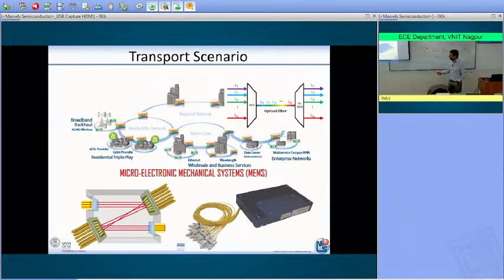However, the time to switch from one port to the other is a few milliseconds. The reason is that you need to control the mirrors in a very precise way in order to align the light output to the proper fiber. It is the time that it takes the mirrors to align and steer the beam to the proper fiber that determines the speed at which the rerouting occurs.